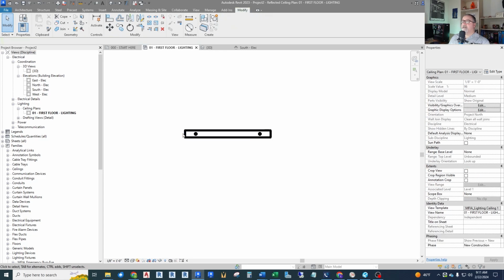But for other kinds of light fixtures, I may want a different symbol. Like if you watch my exit sign, I'll put a card up top to help you get to the exit sign that I created. Its symbol looks entirely different than its extrusion. It's a circle symbol for a rectangular extrusion. So that is what becomes more apparent using a symbol. And my symbol will scale with the light fixture, so the symbol will be the proper size.